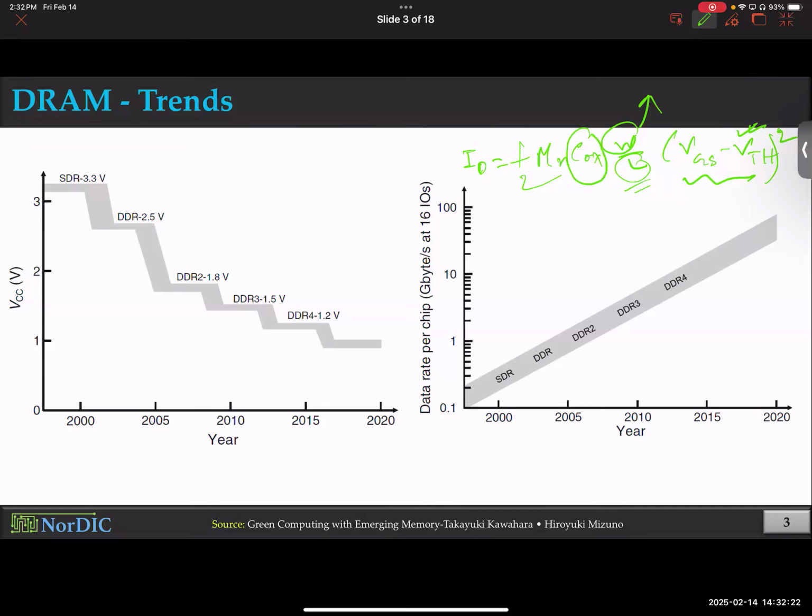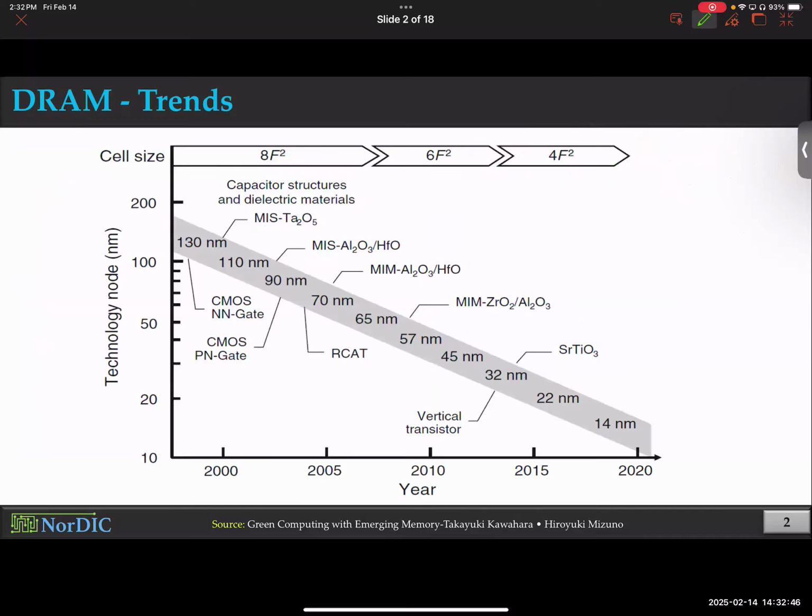Oxide capacitance is something that you can change. Cox is the oxide capacitance. And what is that oxide capacitance, folks? In a transistor, the reason it is called MOSFET is because you have a metal, you have an oxide, and then you have semiconductor, right? And that oxide that's in the name, if you change that oxide, your Cox will change. And I didn't talk about it willingly. I want to get back here.